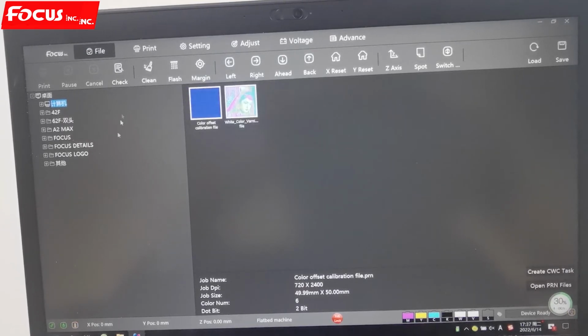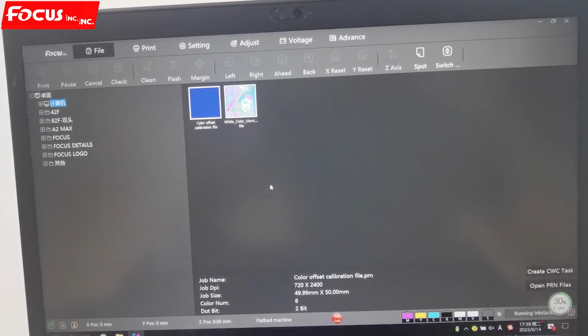Otherwise, we will waste a lot of ink. If you are not using the machine for a long time, you just click off and do some maintenance job later. So this is only used for when you go out for several hours or half an hour. And when we click again, then we can close the flushing. When we close the flushing, the carriage goes back to home position, and the cap station moves up to keep wet to prevent the head clog.